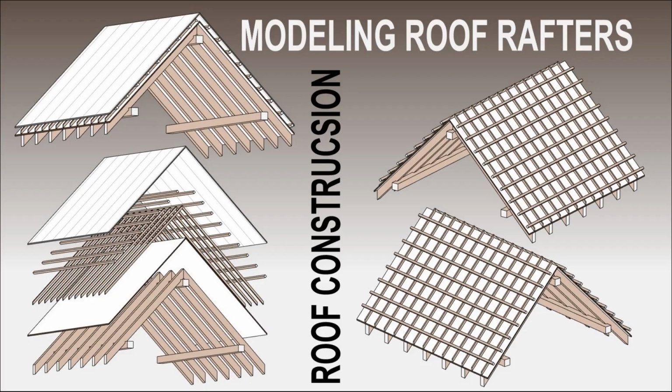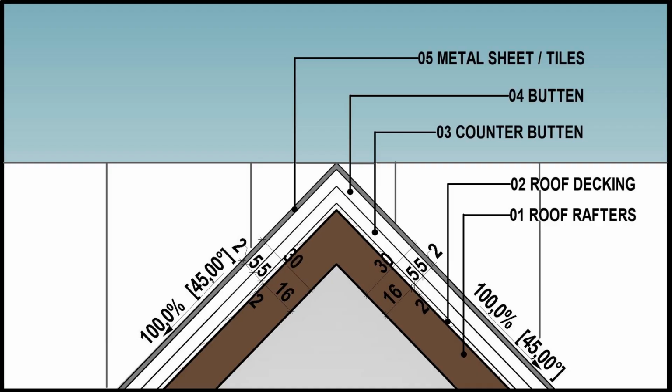roof elements. Before you start modeling the roof structure, it is important to first model the roof using the roof tool with all layers and to determine the thicknesses of the layers. And we will use that roof as a reference for the roof construction that we will model. That's going to make our job much easier. Here you can see I already modeled and prepared the roof, and here you can see the dimensions and thicknesses of all roof layers.